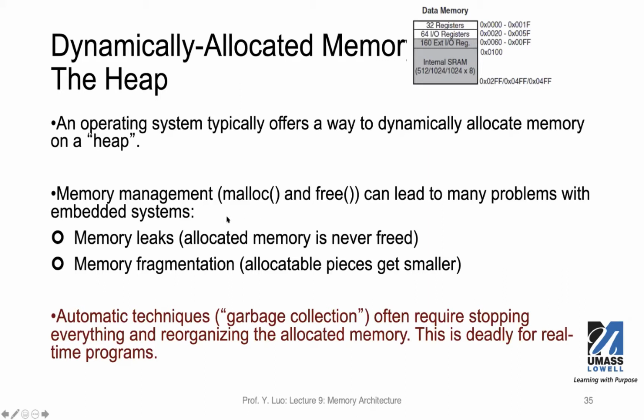Eventually, you're going to use up all the physical memory in your system. It may also cause memory fragmentation that will prevent you from allocating larger space if you don't free enough space that you requested earlier. There are techniques for managing this more efficiently, such as automatic garbage collection. It requires stopping everything and reorganizing, but that's not really very useful in the embedded domain, especially for real-time programs.